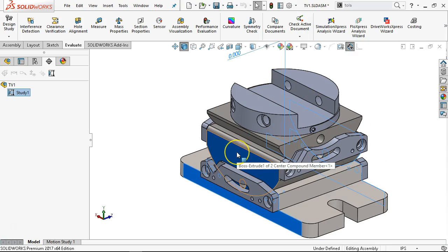based on the tolerances from the dim expert, the next step is to, well, last time I did this anyway, the next step was to generate the report that would say, if this went to its maximum material condition, this went to its minimum, what is your remaining clearance? Or what are the values? If this went to its minimum material condition, and this went to its maximum material condition, what is now the gap tolerance?